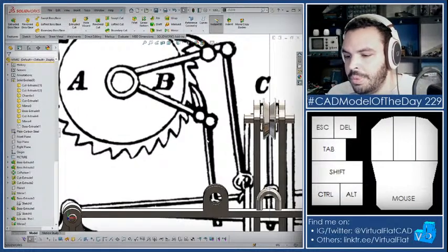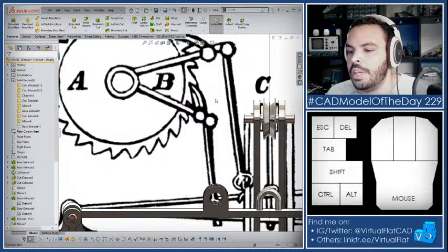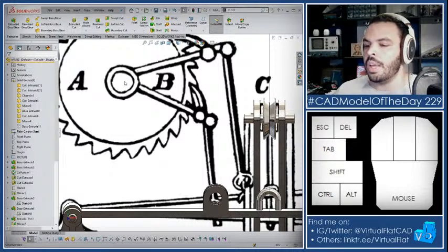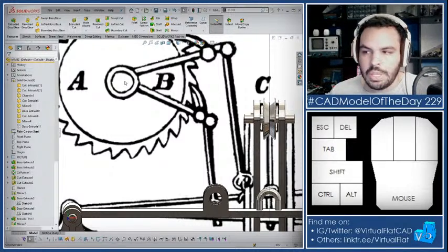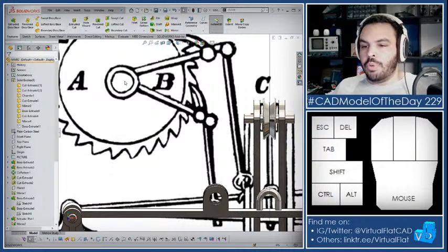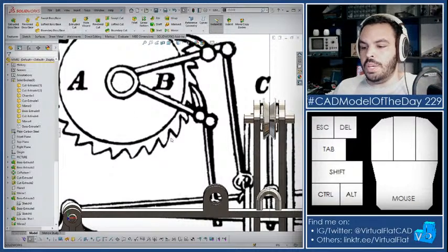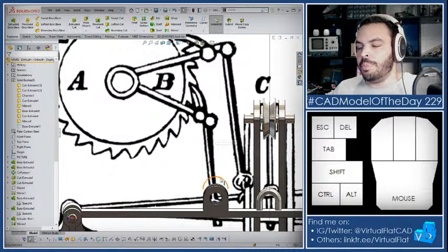It's really, really hard to tell because from here to this circle is link 1. From this circle to this circle, I think is link 2. That's what it has up here. Like clearly that's a link. So 1, 2, and then from this circle to the center, that's link 3. And well, you might be saying, that's only 3 links. Where's link number 4? Well, 4 is what's called the ground link, and that's where you fix your mechanism to. So that's from here all the way back here. So this is a 4-bar mechanism, actually.